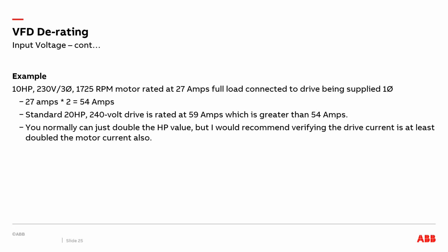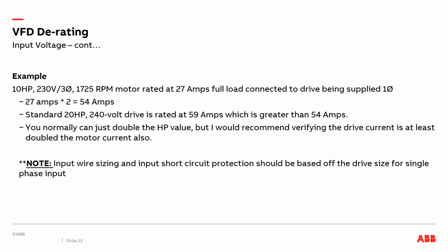You can normally just double the horsepower like I mentioned on the previous slide, but I would always recommend verifying that the drive current is at least double the motor current as well. One big note though: when you're doing this single phase input voltage to a drive, you have to take into account that the input wire sizing and input short circuit protection should be based off the drive size for single phase input, not just the motor size.